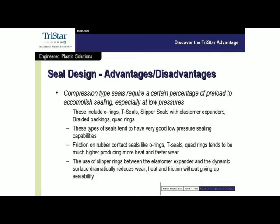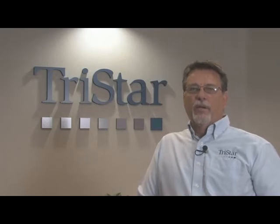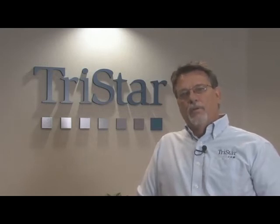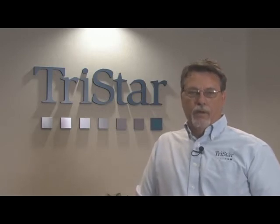The use of these Teflon slipper rings between the elastomer expander and the dynamic surface obviously reduces the wear, reduces the heat and the friction without giving up that low pressure sealability. So it's a nice combination of sealability, wear performance, keeping the heat generation down by keeping the friction down.